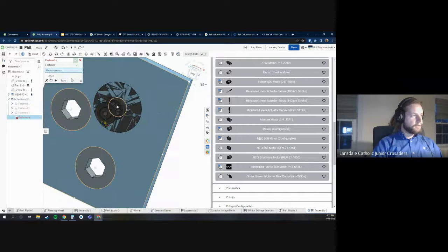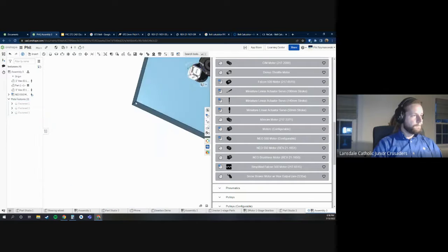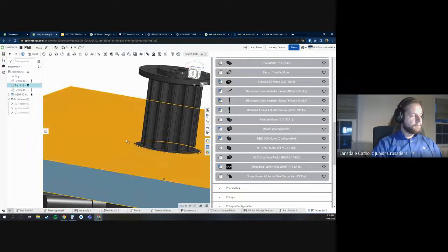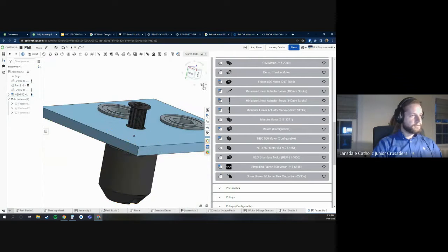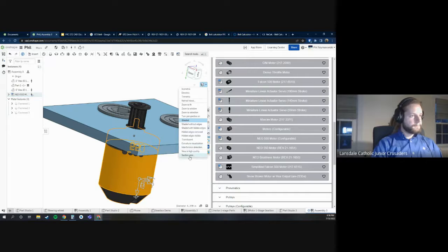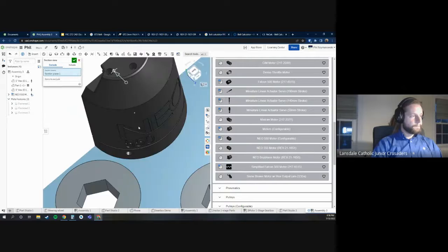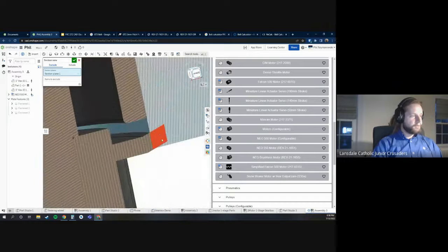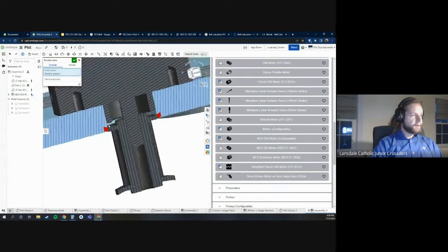I can do it that way, or I could do it, oops, flipped. So now I've got the motor here with the pinion. Oh, there's a little bit of a problem, and I'll do a little cross section here. You can see what I'm showing. Do you see how the flange of the GT2 pulley runs into the plate? That's a bit of a problem.